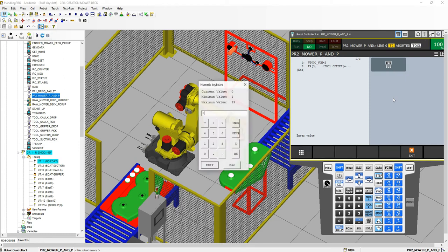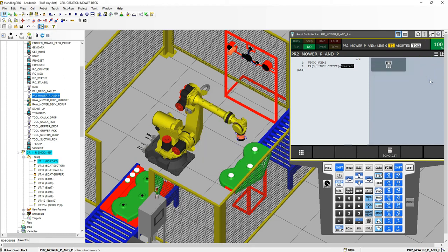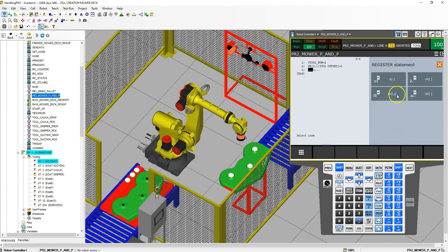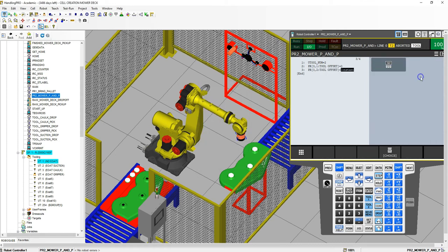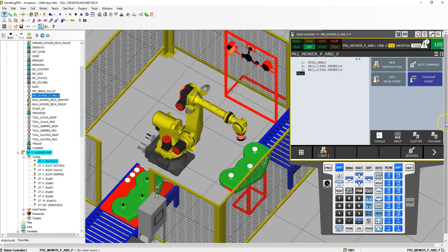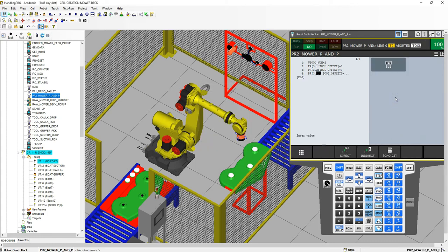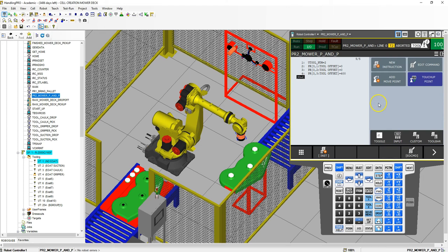So we're going to reset the X first to be 0. Then we're going to do the Y component, number 2, that's going to be 0. And then we're going to have the tool offset be 400. Okay, so we're going to be 400 millimeters above our part. So let's go new instruction, registers equal to position register number 3, and the Z component, we're going to make 400 millimeters. Okay, so we have this set up at each program, so it automatically redoes the tool offset for each program to be whatever it needs to be.